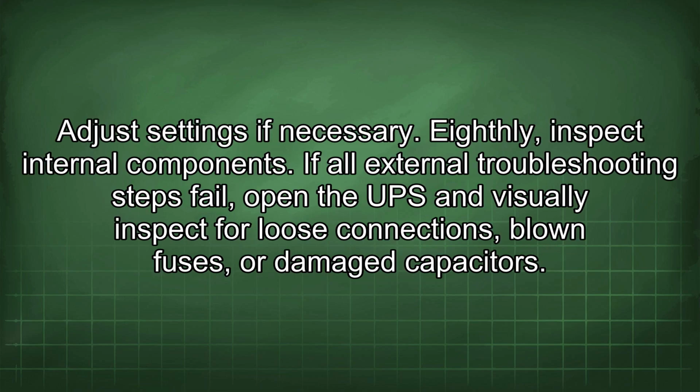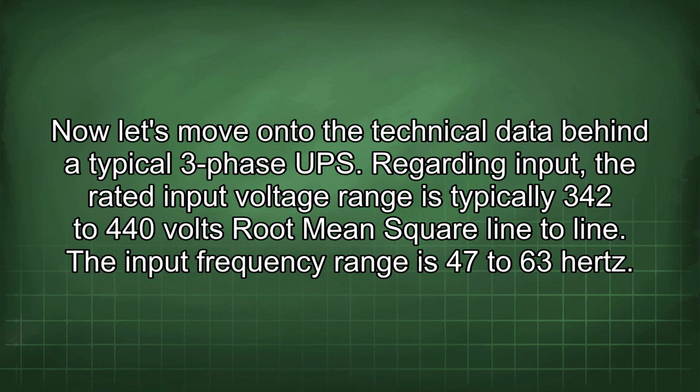Adjust settings if necessary. Eighthly, inspect internal components. If all external troubleshooting steps fail, open the UPS and visually inspect for loose connections, blown fuses, or damaged capacitors. Now let's move on to the technical data behind a typical three-phase UPS.